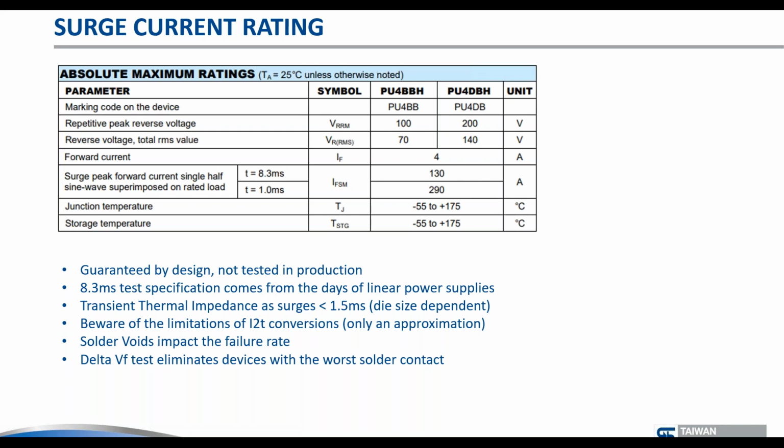What you do need to know, and this is invisible to you, is that solder voids impact the failure rate. If somebody reports a surge failure, the biggest thing you start to look for, usually though not always, is the solder voids. There you really need to know your supplier, and in this case whether their soldering processes eliminated solder voids. We have done that, but maybe not everybody in the Far East has done that. So this is something you need to be aware of.